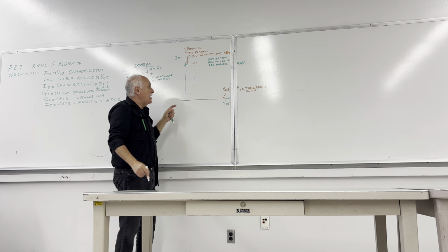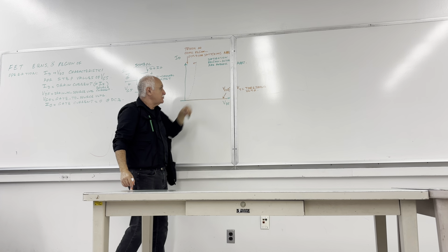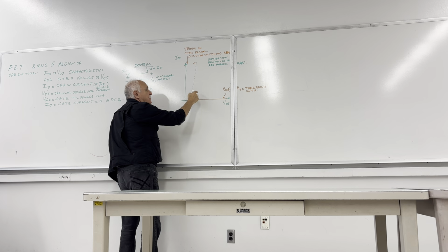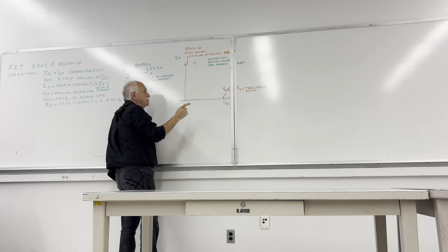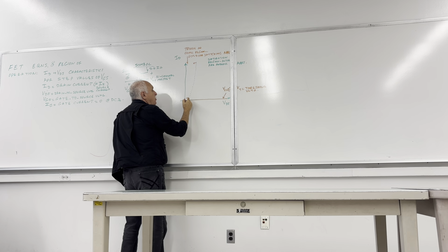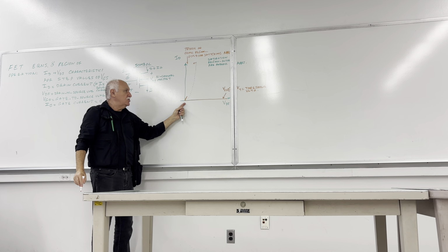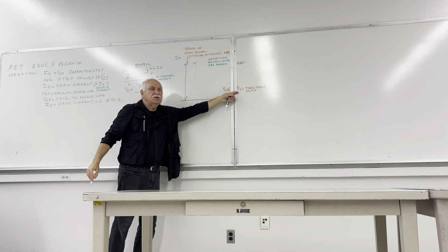Now, after we change the VGS to a higher level, the mode of the current transfer from drain to source changes between two. Number one, initially it will be proportional, just like a resistor, for VGS slightly greater than the threshold voltage.